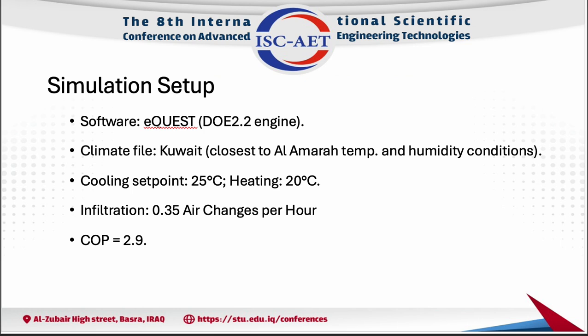The simulation was performed using eQuest, which is widely used for detailed building energy modeling. Because the available Iraq weather file in the software only represents Baghdad and its climate differs from Al-Umara, we selected the Kuwait climate file, which better represents the higher temperature, humidity, and solar radiation typical of Al-Umara city.